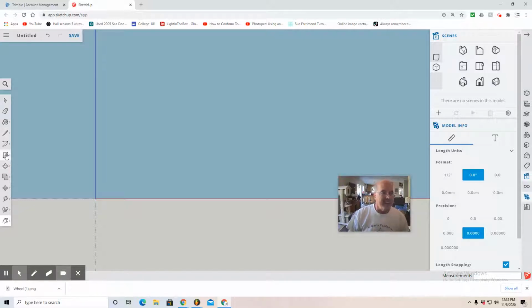Today we're going to create what's called a lever, and I'm going to select rectangle to start. I'm going to start at the origin point and start to move my cursor across. At this point, I take my hands off the mouse because its specific dimensions are 9, 1, then hit the enter key.